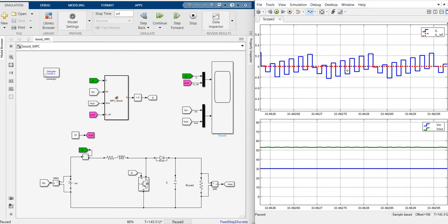the results show that the switching frequency is very high. The switching frequency is equal to half of the sampling frequency. So it is not acceptable for many applications, and the accuracy of the controller may not be good in such an implementation. So we need to reduce the switching frequency to get proper operation.